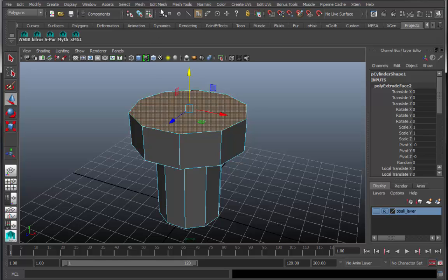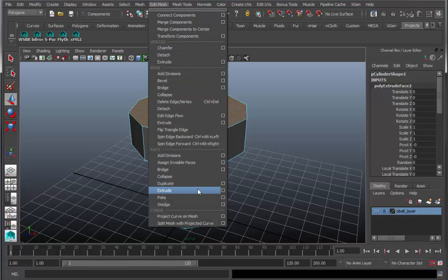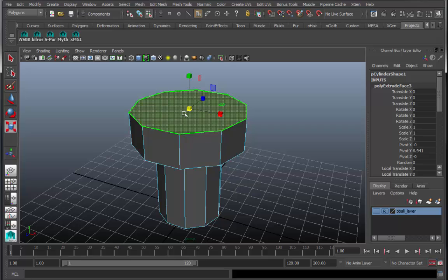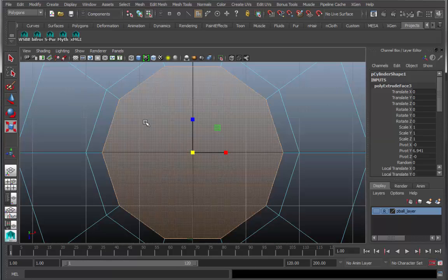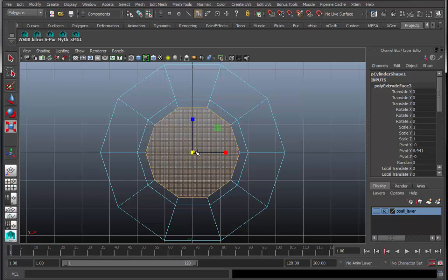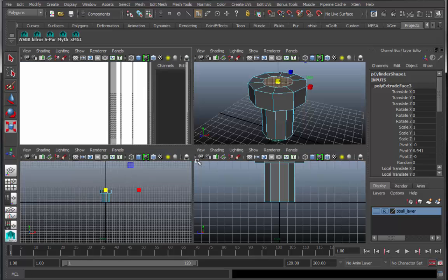The last two steps are that you extrude yet again, and use the Scale tool now to bring things in. You're going to do a final drop down for the interior of the pipe, but as you know, what's very important is that we make the circumference of this circle smaller than this, and the best way to check that is to go into the top view and go to wireframe, press F, and make sure that your current selection is actually smaller than the existing outer stalk of the pipe's trunk.